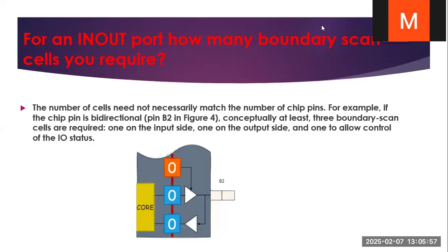This is the continuation lecture for IJTAG interview questions and answers. My first question is, for an in-out port, how many boundary scan cells do you require? This is the most important question. The number of scan cells need not necessarily match the number of chip pins.